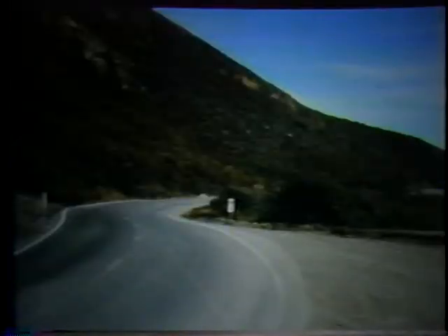Here you see a road with proper super elevation, a condition which greatly affects vehicle stability. When proper super elevation is not provided, as shown in the first curve here, a serious safety hazard can result. Serious steering problems can be caused by a rutted track or drop-off along the pavement. The tire snags on the pavement edge when the driver attempts to steer back onto the paved surface. Oversteering usually results, and the vehicle can cross over into approaching traffic or adjacent lanes.